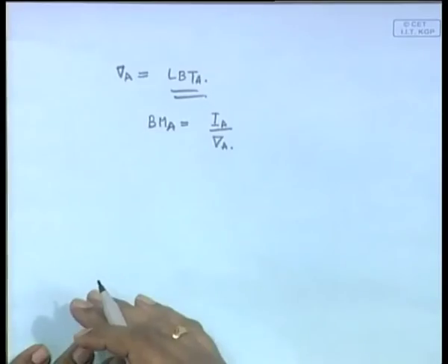But in this case there is an additional thing you have to take into account in the case of added weight, because the water is now in the ship and it is a part of the ship. It is almost as if we are assuming it is a tank, okay. That whole compartment is now like a tank which is carrying the water.